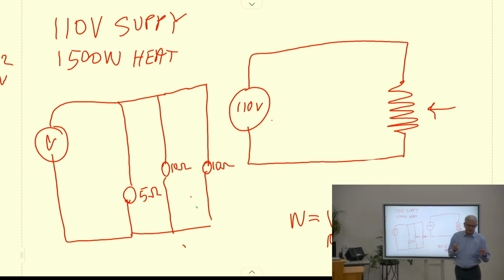And that's what they do, transform from one voltage to the other. And that only works because of magnetism between the primary and the secondary windings of the transformer. Like I said, you can go either way. That's why you can backfeed a transformer. You can step it down. They don't care. It'll mess you up. You can have 12 volts coming back, and all of a sudden you've got, like I said, 1,000 volts in your hand. All these transformers on the user end are stepping down, going from 12,500 volts out there to 240.